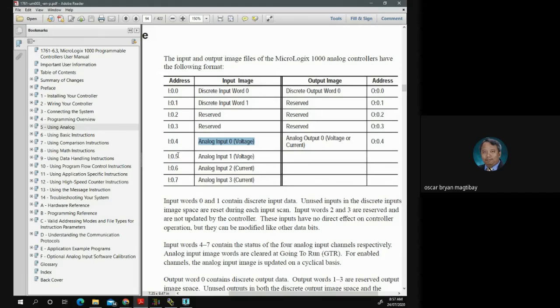A slash, like /1, /2, means that it is a bit. A bit is a field device whose signal is only 0 and 1. But when we talk about a dot, it comprises 8 to 16 bits of data. Because our signal comes from analog and we convert it to digital, the digital values need to give a signal from 0 to 32767.